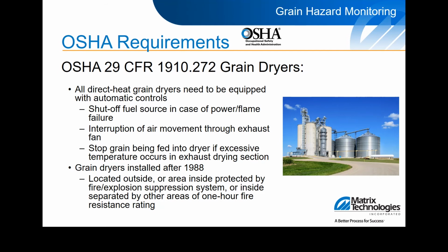It's common in older facilities to see several different vintages of equipment installed. Older systems typically relied on hardwired relay timer logic, whereas newer systems are coming supplied with safety PLCs. It is also common to see older grain dryers abandoned in place, and if they were built into existing head houses, bins, or other configurations where removal of equipment is difficult, they still may reside at the facility. Care needs to be taken to remove any electrical or heat sources to ensure the system cannot be started back up without required upgrades to meet code compliance.